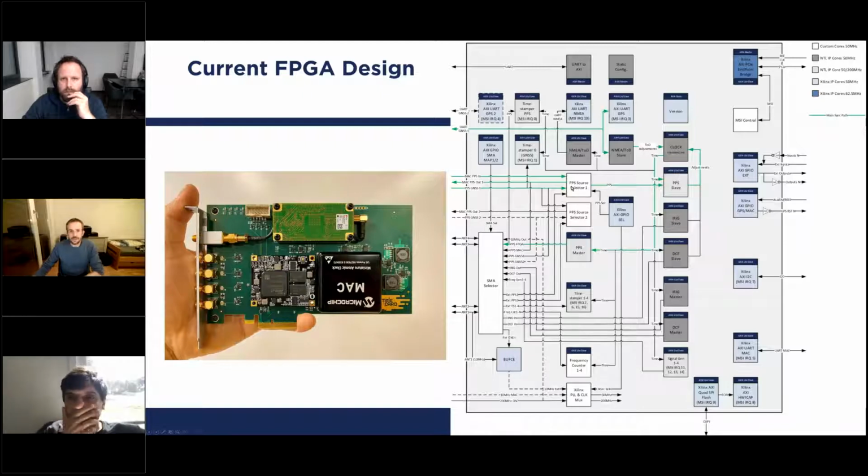I will now quickly show you the main synchronization path of the whole design. So as we have seen, we have here the GNSS receiver. The GNSS receiver provides UBX messages via UART. These UBX messages are provided to a Xilinx UART interface, so this can be accessed by software, or it goes directly into the hardware part, our TOD slave. This TOD slave extracts the time of day information from the UBX messages and provides it to an adjustable clock here.